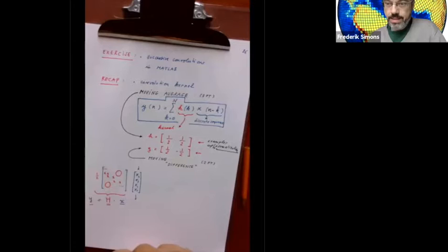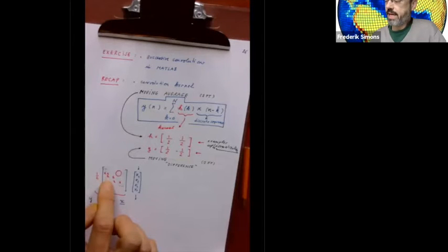So 2 at a time. But the convolution, it repeats that operation. And so you want to flip the filter backwards and then roll it around down the diagonals of this matrix and then keep going forever. And the output only ever gets you the combination of 2 elements, but they're 2 successive elements of moving averages.